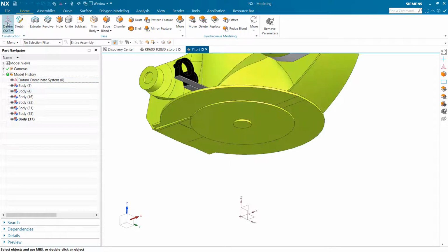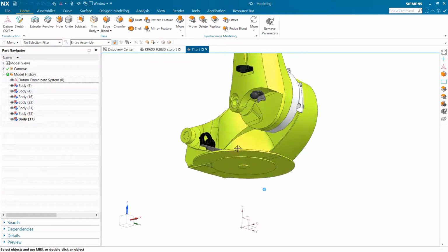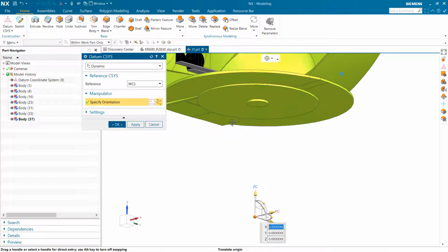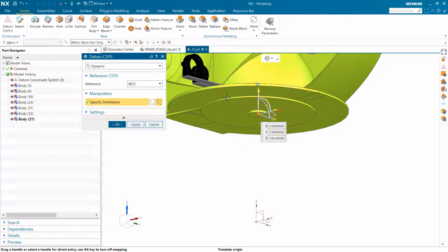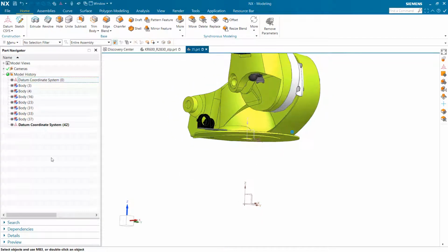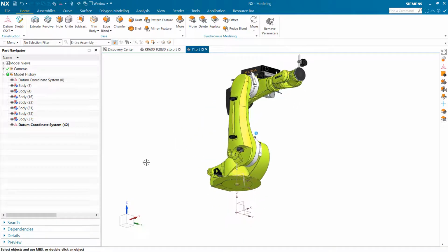So the next coordinate that I would like to use is the center of rotation for this geometry, this graphics. So let's create a new coordinate system at the center of rotation as such. Probably at, yeah, as such. Then we have two coordinates. Again, my advice is always to put the center of rotation at the origin location, so that when we transfer the graphics into plant simulation, the workflow will be much easier. So for now, I will just quickly do some transferring.